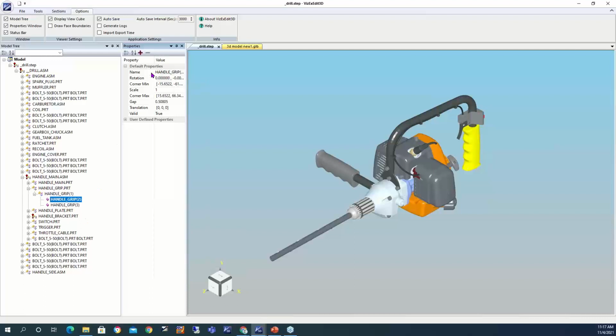You'll notice as well here that on the properties it shows me the name and some other information about that particular part. The reason we did this is that we thought you might want to change the model tree name. So it's got a handle at the moment, but this would allow me, if I double click in here, to actually change the text in here. So we could actually amend the model tree when it comes through into the viewer, which is really useful.